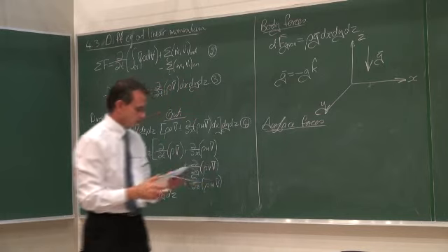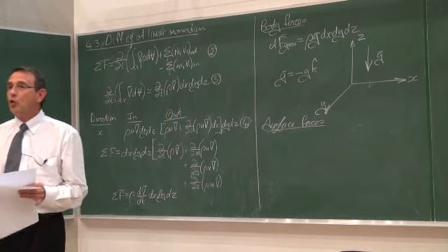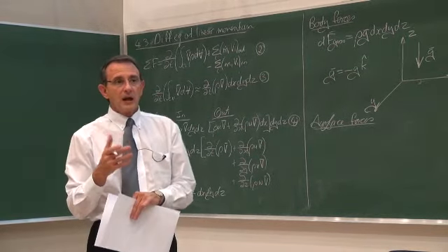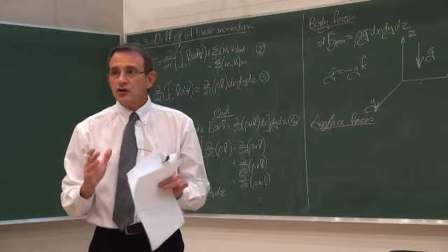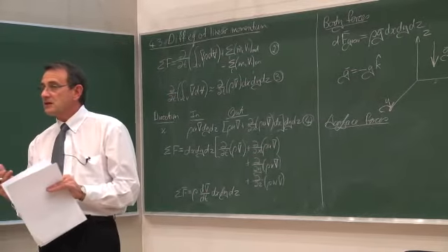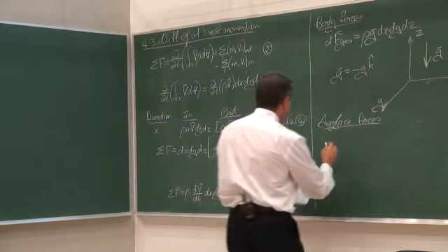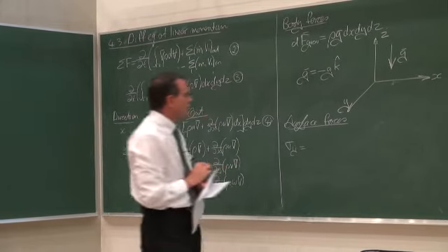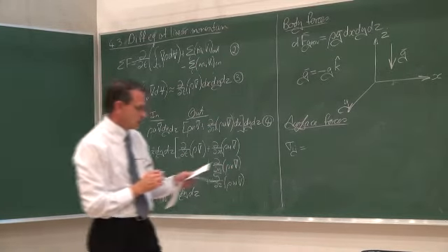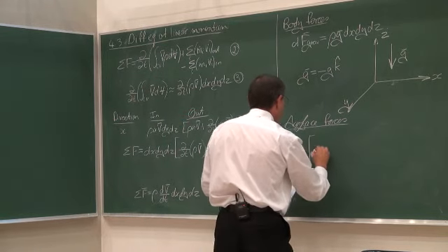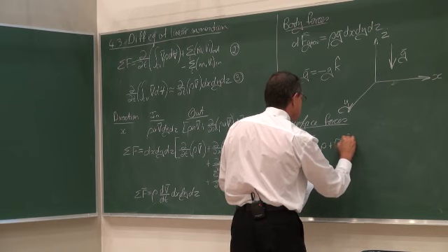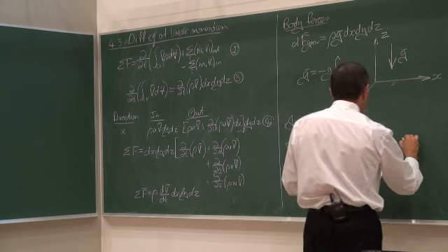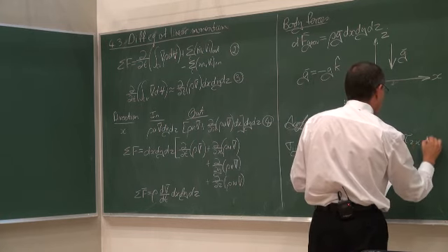The surface forces. And that's now a little bit more complicated. The surface forces are directly proportional to the surface tensions multiplied by the areas. And this is now where things become more complicated. What we use is this type of nomenclature, by saying that sigma ij is equal to, the first term is minus p plus tau xx, the second one is tau yx, and the third one tau zx.